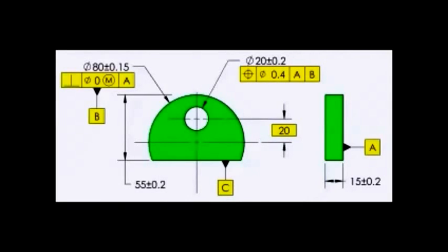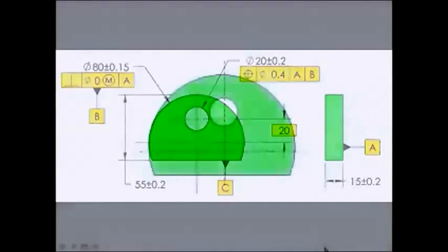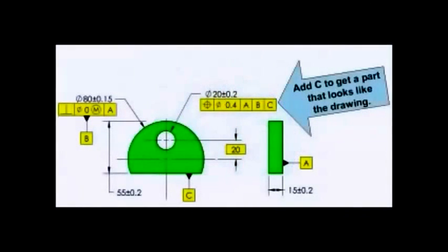Yes, the hole is shown on the center line that is perpendicular to datum feature C, so we know what the goal is. But since datum feature C was not referenced in the position tolerance, there is no limit to how far the hole can be off the 90-degree angle. In order to avoid this, all you have to do is add datum feature C to the position tolerance.